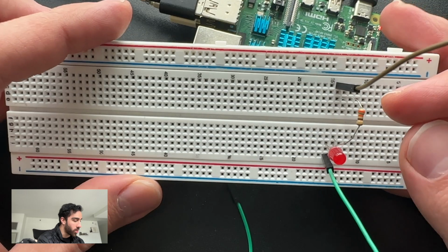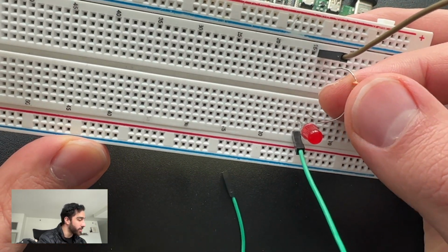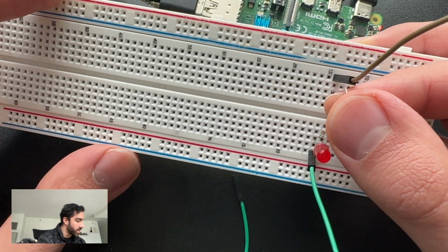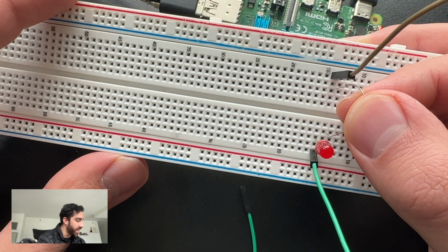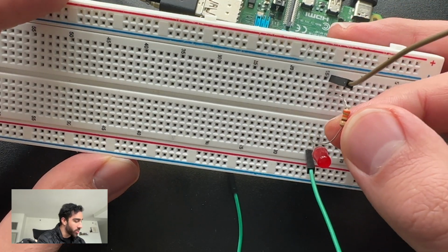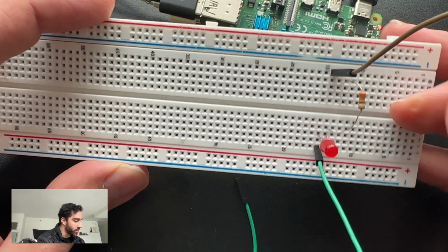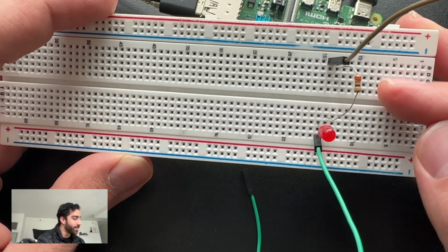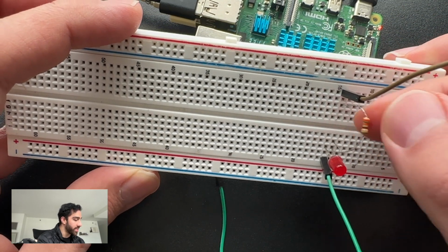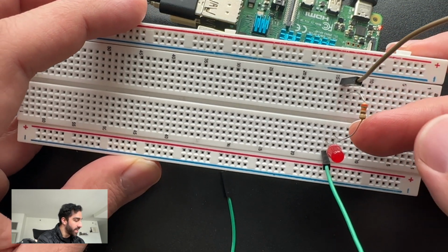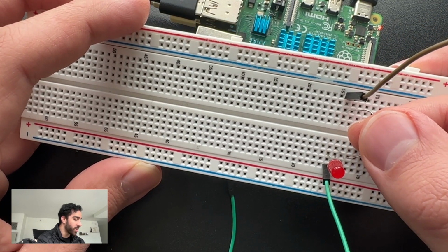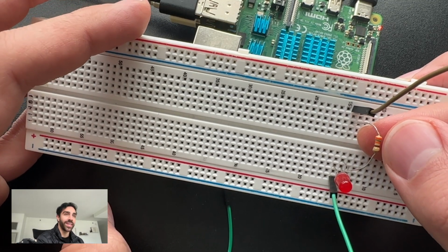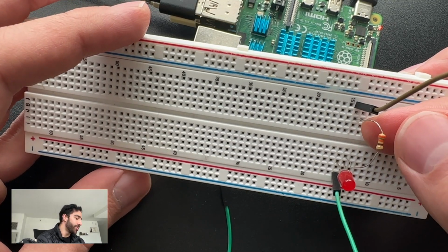So we have a resistor on the board, and we see that both ends of the resistor are on the same row. I'm just using row 16 it looks like, but make sure one end is on one side of the bridge and one end is on the other side of the bridge, because as you see in the center of the breadboard, it's not connected from one side to the other, but you can connect both sides with a resistor like this. So it's taking current from this side and reaching the other side. That's what's nice about this resistor, it does protect the LED from potential burnout. Not that we care too much about these LEDs because they're very cheap, but it's just better to use those.